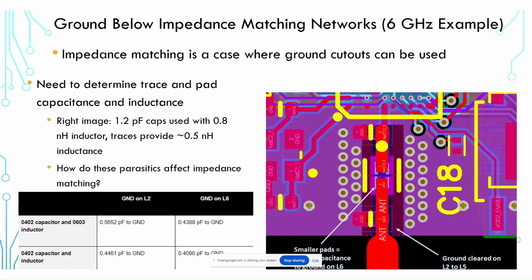Now, if you're dealing with an RF design, that RF trace needs to be treated in a very similar way as the digital trace. The ground should be provided close to that trace, and that will help confine the return current from that RF interface. Here we're showing the signal coming out of a microcontroller, and you can see the edge of the microcontroller in the upper half of this image. That trace is passing over ground, and it's basically a coplanar waveguide.